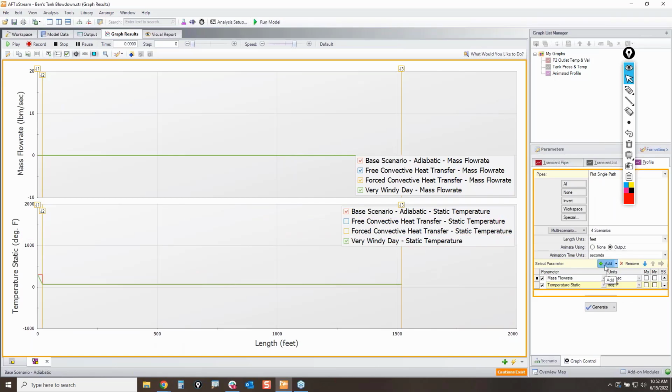You can also maybe do a third graph where you're looking at pressure in PSIA and then maybe PSIG. So if I move this over for the second row right here, I indented it, as you can see. That's going to create a secondary y-axis for this pressure, and we're going to set that to PSIG units.